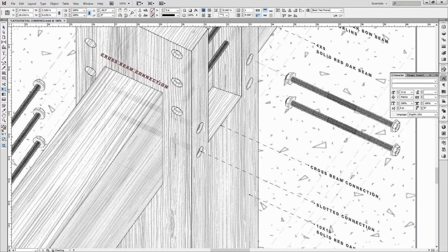So what you'll do is first match this angle. I'll just press E, rotate it, like that. It's still not there. Maybe like that, okay? So this angle here, you see, it's around 25, probably less than that. It should actually be 24. Negative 24. There you go. Negative 24.5. Okay. So that's my actual rotation angle. And then my shear angle will be the same. I'll make that 24. Negative 24. You see? So they basically match. Negative 24, 24. So that I have this going in the same orientation as my drawing.